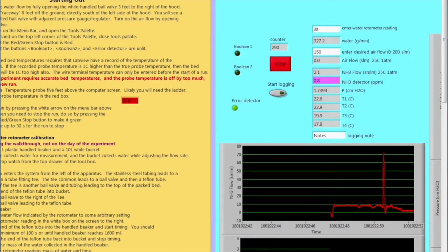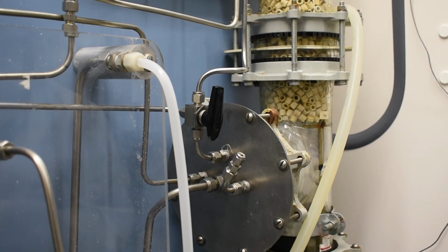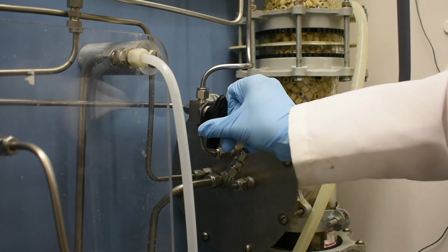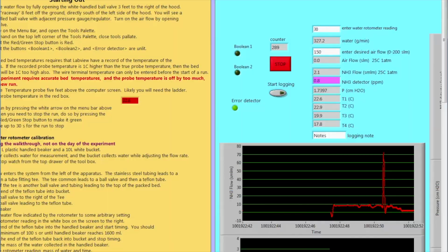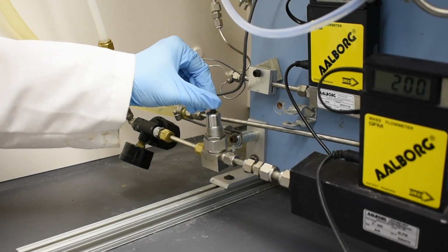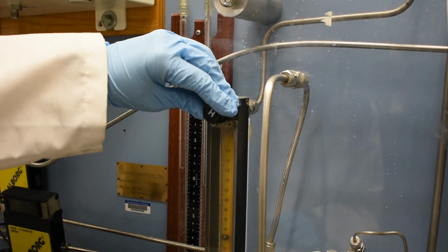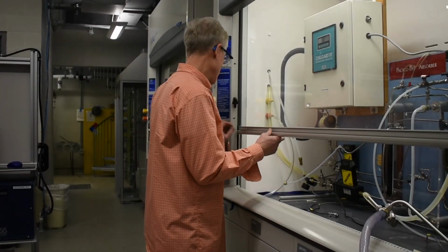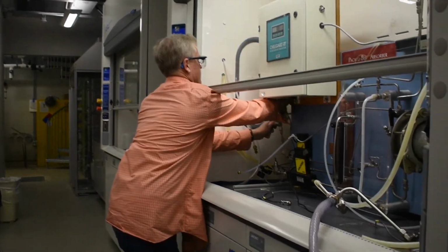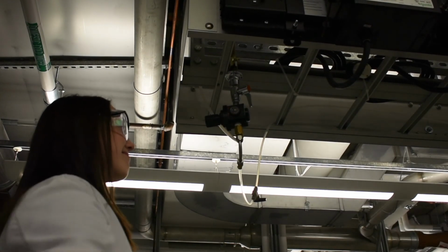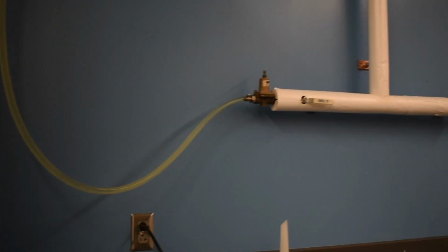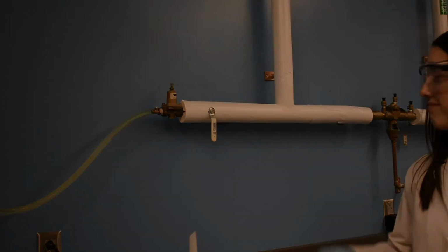Using the charts provided on LabVIEW, wait for the ammonia concentration to stabilize. Once the ammonia concentration has stabilized, point the three-way valve to face towards the top of the column. Wait for the ammonia concentration to stabilize. For the pressure drop trials, the procedure followed will be the same, however, the ammonia supply will be turned off. For shutdown procedure, make sure the professor turns off the ammonia supply. Additionally, make sure that both the air and water supply valves are shut.